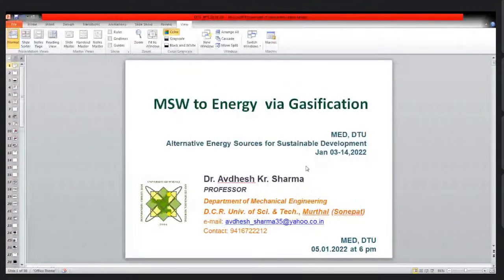At present in villages, this technology is basically dedicated for villages, but for municipal solid waste in urban areas, in metropolitan cities, there is a huge problem. When we convert a dedicated biomass gasifier to a different low calorific value fuel, the performance is definitely hampered, but we need to mix and calculate some proportion of biomass as well as RDF or municipal solid waste that can be used.